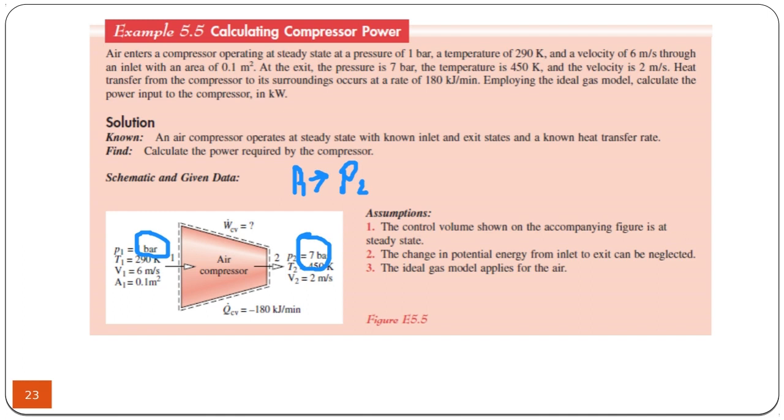And due to the compression, the temperature of the air increases because, according to the ideal gas law, you remember that there is a relationship between the pressure and temperature of the air. So at the end of the compression, you should expect that not only the pressure but also the temperature will increase.